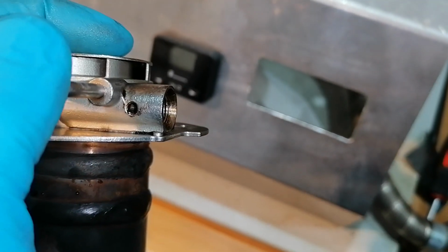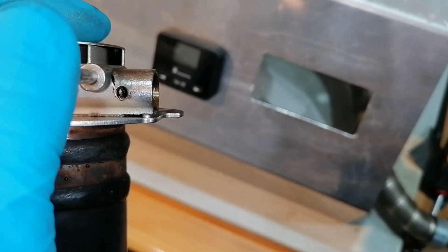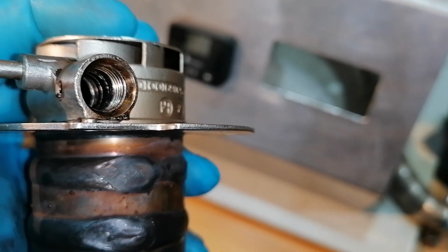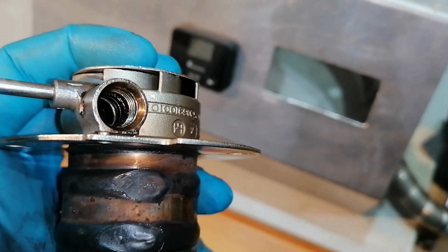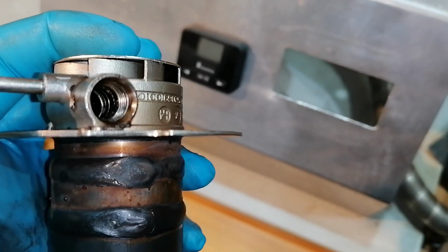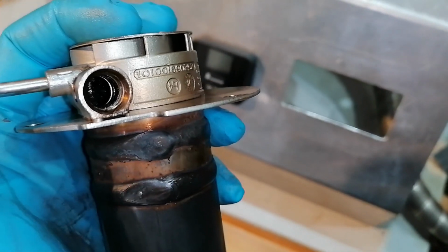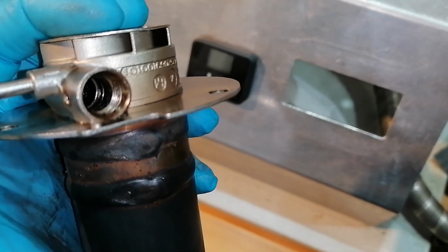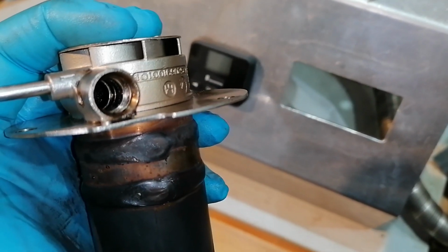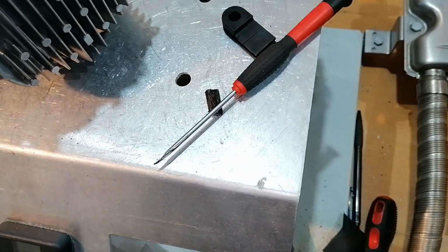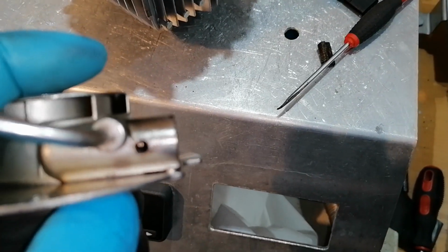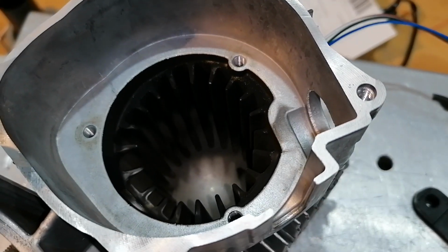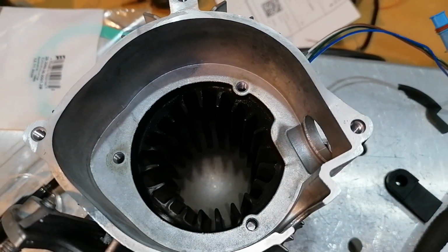Okay, so we cleaned this burner up. We cleaned the hole, and also, if you look closely at the bottom, you can see there's a channel, or some kind of channel right after the strainer. This also has to be cleaned very well. Usually workshops miss cleaning that, and just change the strainer. Also sometimes they do not unplug this hole. Okay, we clean this also.